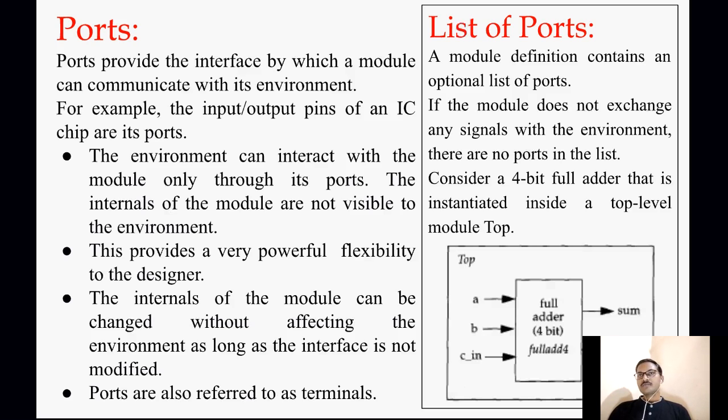Now the ports provide the interface by which a module can communicate with its environment. For example, input or output pins of an IC chip are its ports, as we have seen in this figure of the 4-bit full adder. The environment can interact with the module only through its ports. We are going to define a module, and we will communicate the signals with the help of its port list.